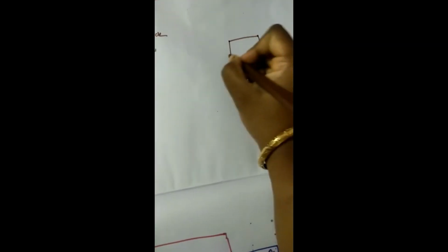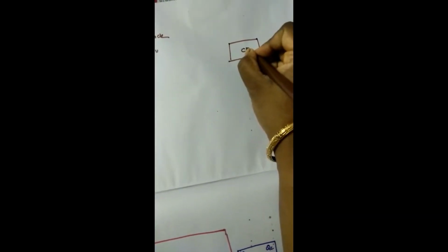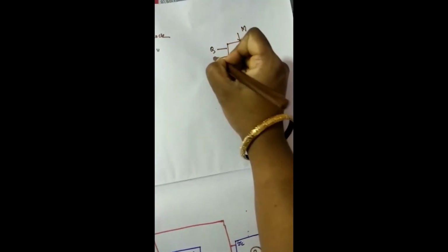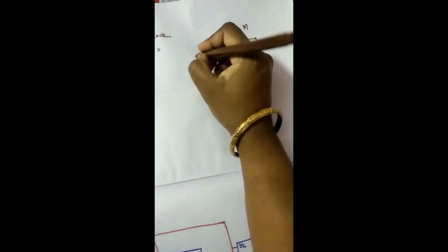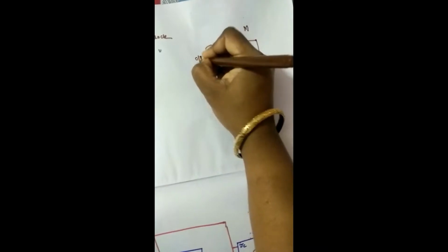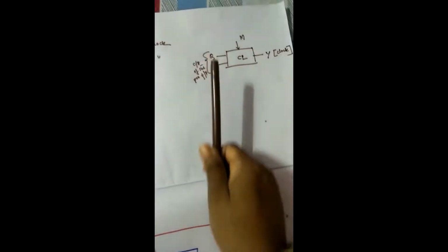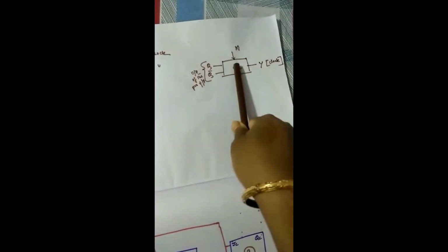So basically, if we consider the circuit, this is a combinational logic circuit, where we take a control signal M and two inputs Q and Q bar, and these inputs are the outputs of the previous flip-flop. And this is the output Y. This Y is connected to the clock input of the next flip-flop, right? So now we have to design this combinational logic circuit.